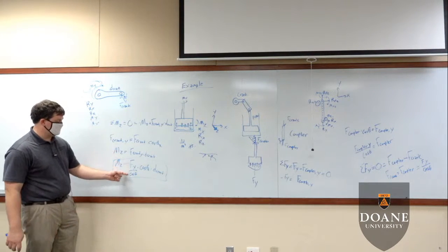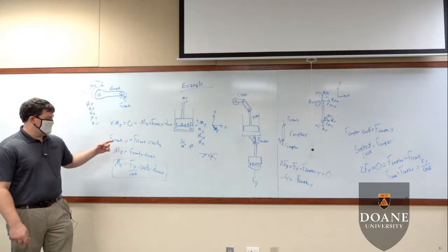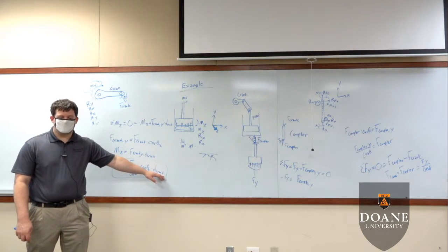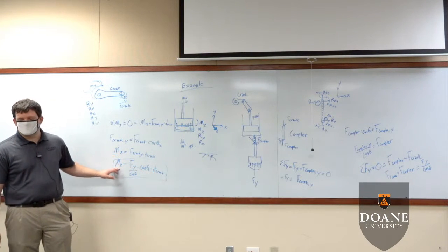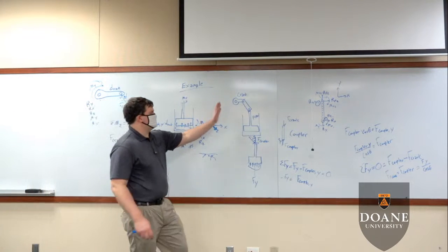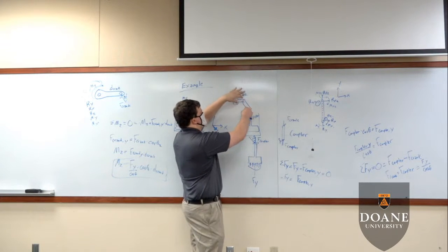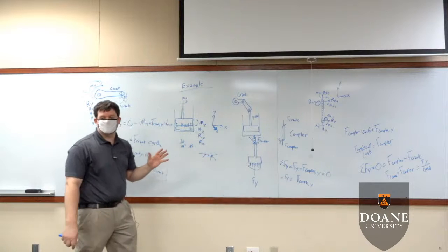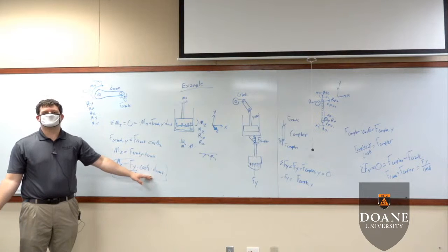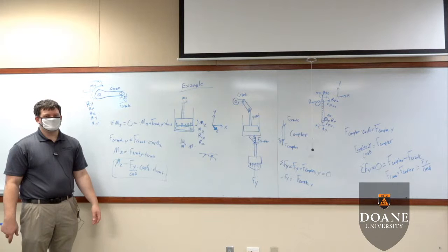MZ is equal to Fy over cosine theta times cosine theta 2 times D crank. If you want to increase your MZ value, you increase your D crank. The longer the crank is, the more moment is being exerted as output. Theta is going to change between maybe 0 and 70 degrees. You can adjust the geometry to limit what theta is between for your coupler. Theta 2 is going to go between 0 and 360 degrees, so there's no way for you to really change theta 2. That's just going to happen.